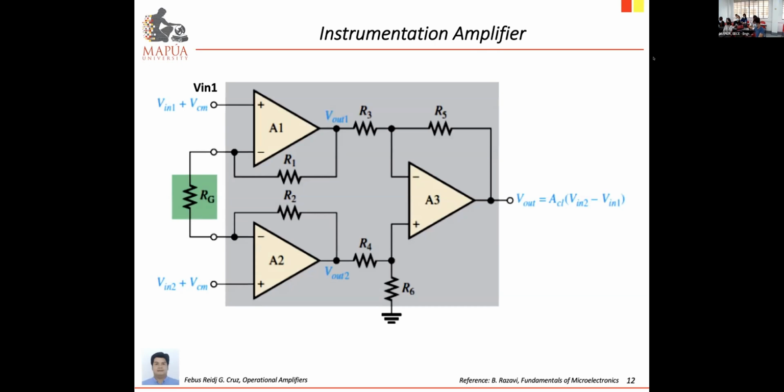So again, for the instrumentation amp, we actually have 3 subtracting amplifiers. The advantage of having a subtracting input is the common mode rejection ratio or the noise rejection capability. So amplifier 1 will be able to cancel any noise from V-in1 and from any noise on this input. And amplifier 2 will also provide the noise rejection. After that, you have the second degree rejection.